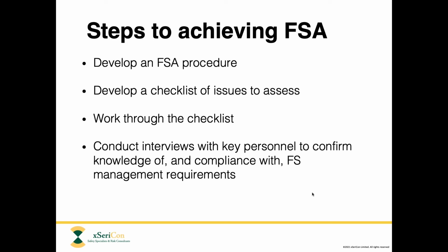They need to know what it requires of them, what their responsibilities are, and we need to be able to see evidence that they're actually implementing the requirements of the functional safety management plan. Because the management plan is not meant to be a great big thick document that just sits on the shelf and does nothing except achieve a tick in a box. It's supposed to be a living document that actively guides the team through the functional safety life cycle.